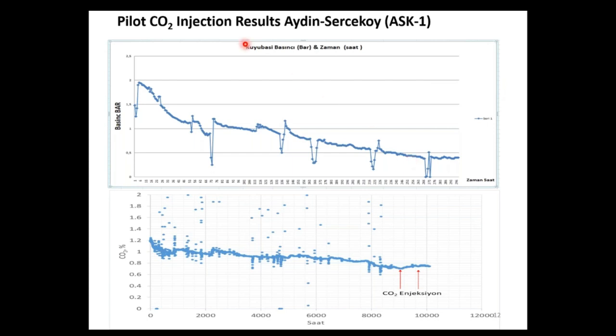As you see, you can see the effect here very sharp, and then stabilized. If you go further, maybe it's going to be pretty much stabilized around 0.5 bar, since the near wellbore improvement is already completed, and then it is maybe very slowly going to stabilize.